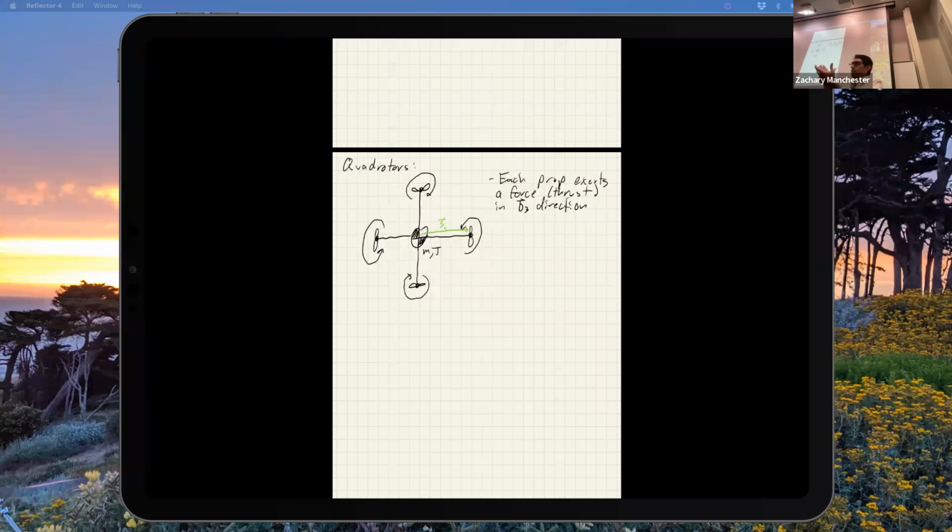What it's actually coming from is, the way to think about this is each propeller blade is actually a little wing, right? So the wing generates lift and drag. The lift is your thrust. The drag on the propeller blade ends up being your torque. Does that make sense? So it's literally I'm getting drag and it's spinning around. The drag force is acting against the motion of the prop, and as I integrate that around a rotation, I get a torque. Clear? So literally propellers are just little wings. They're little airfoils.